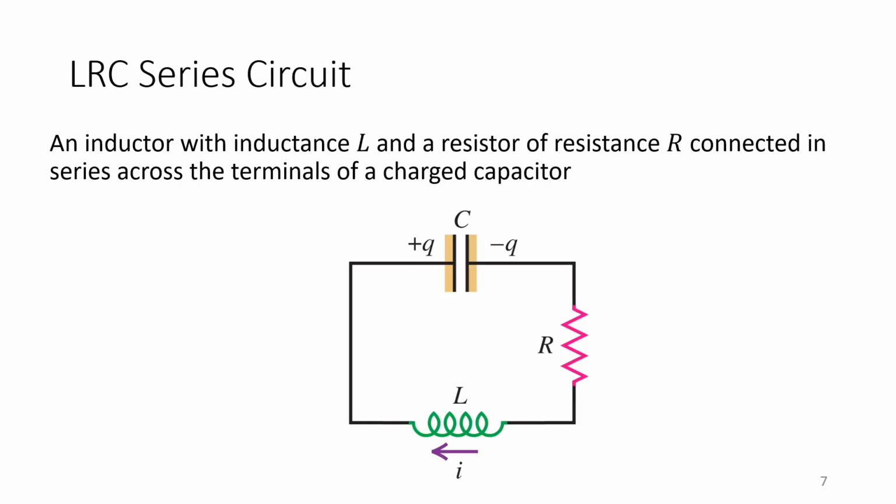Now we introduce the LRC series circuit as the LC circuit with just a resistor added, as was drawn a while ago. The order of placement shouldn't really be important because when you do Kirchhoff's law, you could rearrange the terms later, so we'll get there in a bit. A resistor may not even be included, considering that instead of having a resistor, we consider the internal resistance that the inductor has, or the resistance that the wires possess. And one more thing, for the purposes of this lecture, we won't include the power source in the differential equation. So now it's just a capacitor, a resistor, and an inductor.